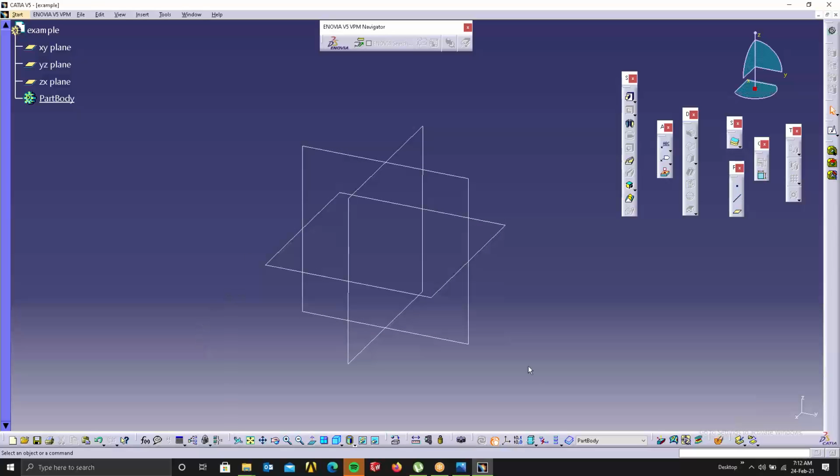Okay, for example, if you have six holes with the same pitch, what people do is they open the sketch, they draw a circle, and they create those holes, meaning those circles. In the sketch option we have pattern, right? In SolidWorks also you have a pattern option in sketch. They use the pattern option in sketch, and they extrude it. So they get the cylinder shape along with the holes.